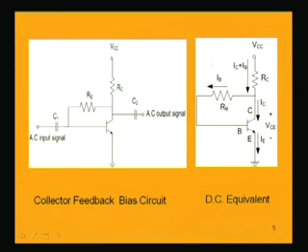So, for this equivalent circuit, the currents as shown, the current through this RC will be IC plus IB, because here this base current is flowing into the base and the emitter current is IB plus IC, that is the emitter current. The current which is flowing into the transistor must be the same emitter current, because that is the current which is outgoing from the transistor.